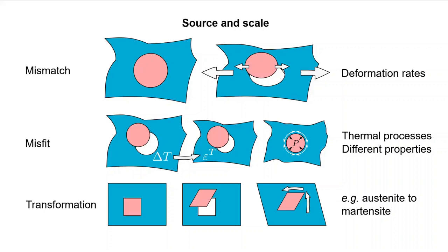It is apparent that there are some of these sources that can operate on different length scales. Bulk plastic and thermal processes occur at all length scales, and the collective behavior of a transformation will cause far-field residual stresses. This gives rise to the need for classifying the length scale over which these stresses equilibrate and therefore affect engineering properties.